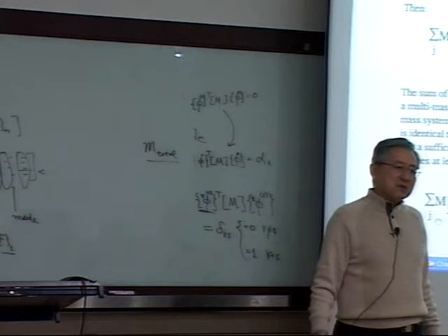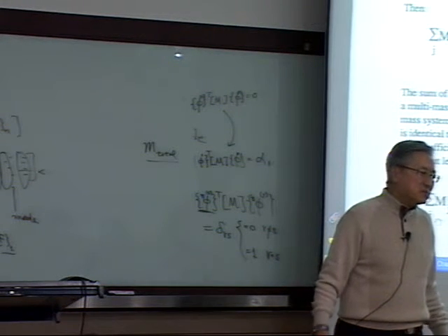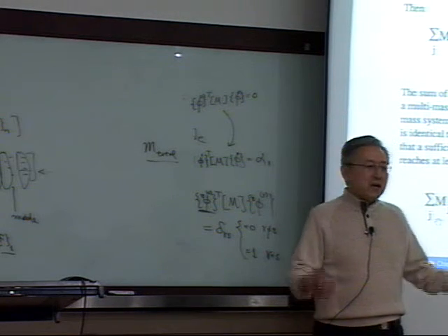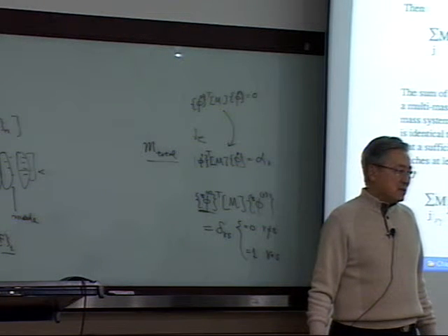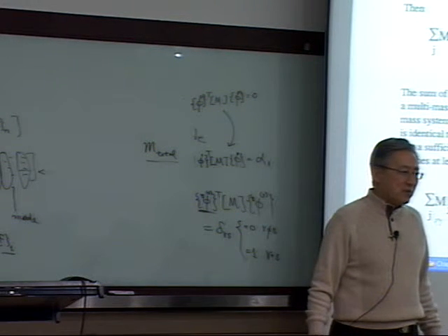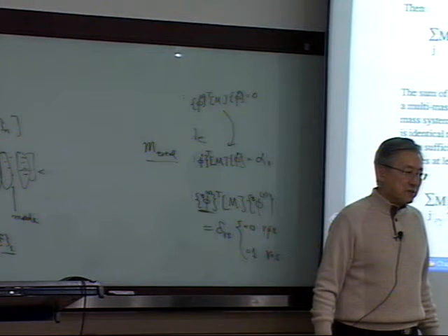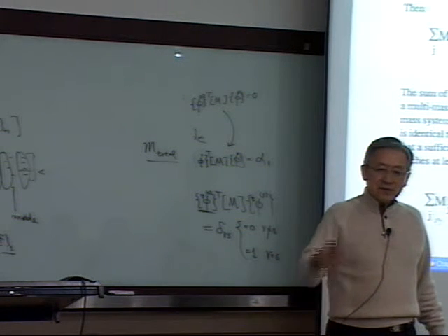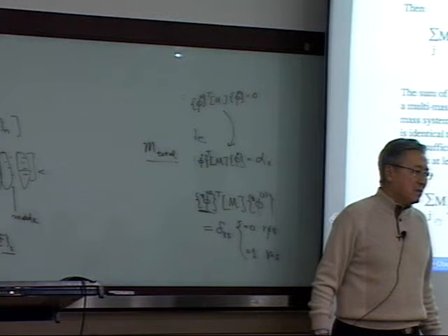So picking out the number of modes is so important. For 1 million degrees of freedom, you have 1 million modes. You don't want to work on all of them, because we know from the modal participation factor that as J goes higher, the modal participation factor is almost zero.